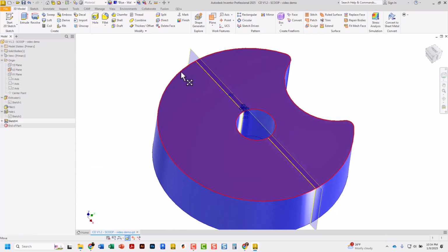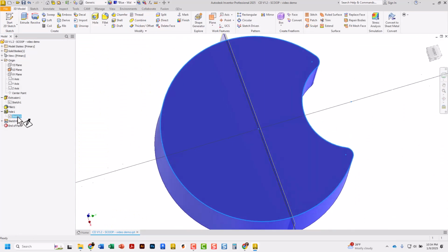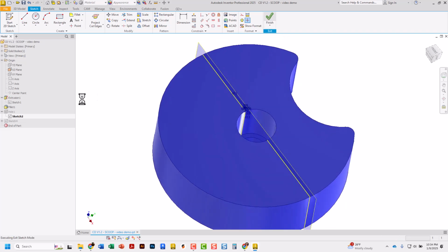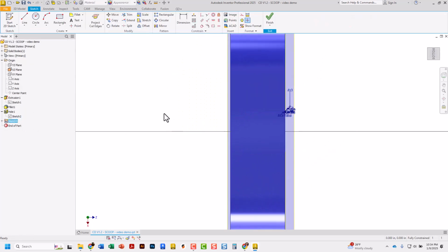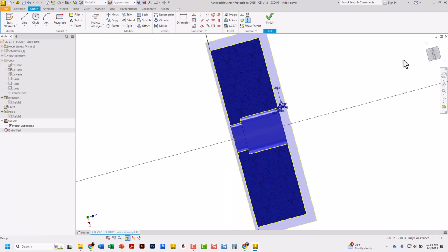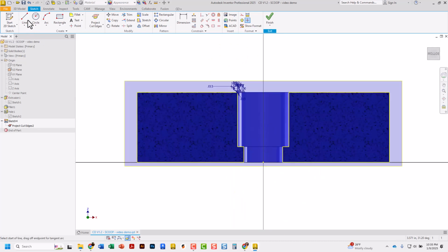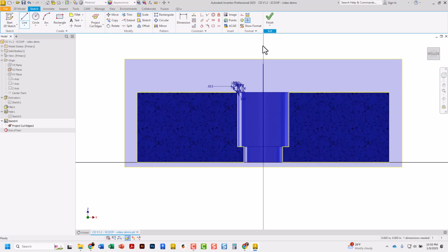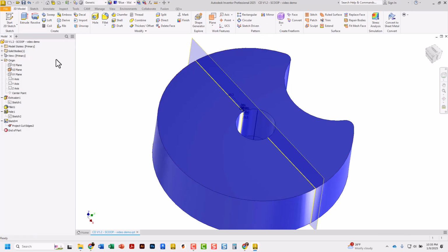So finish. Oh, except I forgot one thing too. Sorry. Messing up here. Let me get back into my sketch I was working on. F7, rotate. I need an axis line to coil around. So right down here I see I got a midpoint. Just draw that up nice and big so it's easy to select. And then I will be able to coil right there.